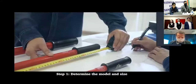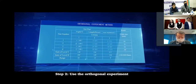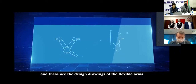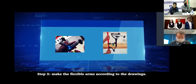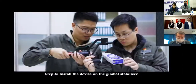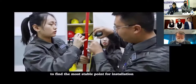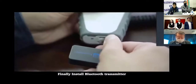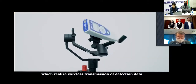Step 1. Determine the model and size of the 4 parts of the detection auxiliary tool. Step 2 is the orthogonal experiment to design the flexible arms. And where are the design joints of the flexible arms? Step 3. Make the flexible arms according to the joints. Step 4. Install the detector on the gimbal stabilizer. Step 5. Use the golden section method to find the most stable point for installation. Then assemble all components. Finally, install Bluetooth transmitter, which realizes wireless transmission of detection data.